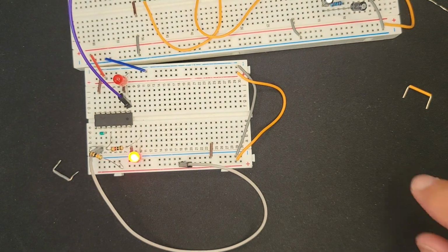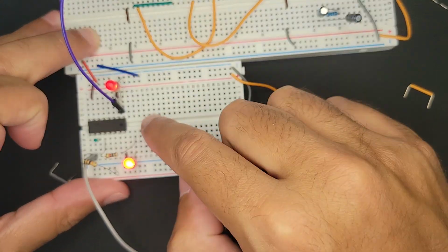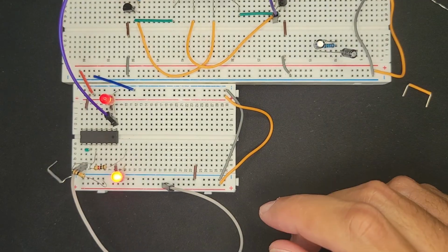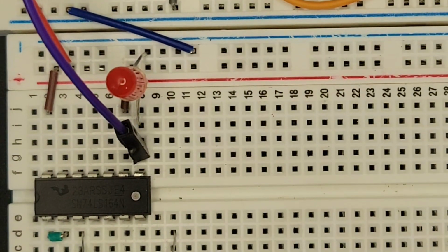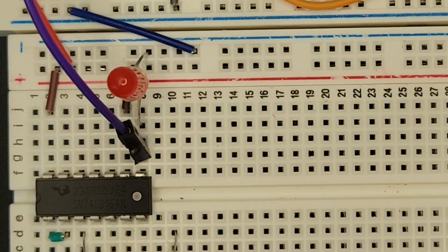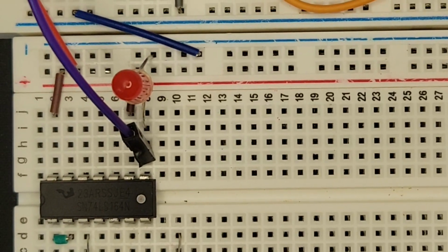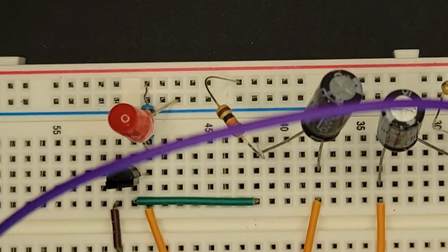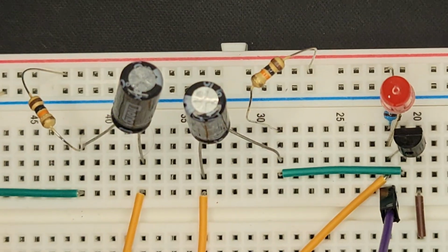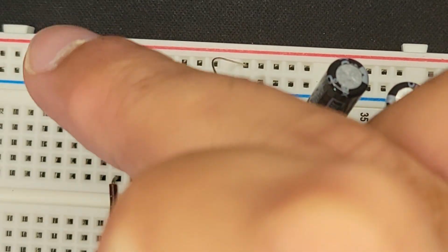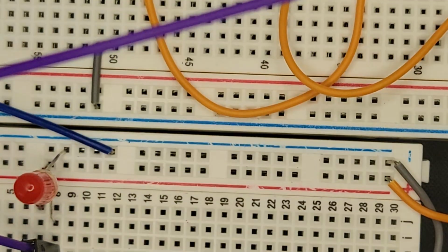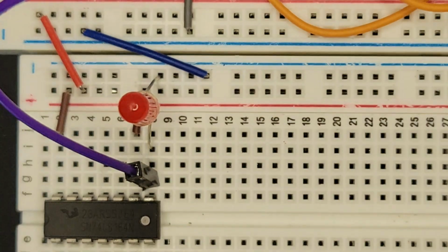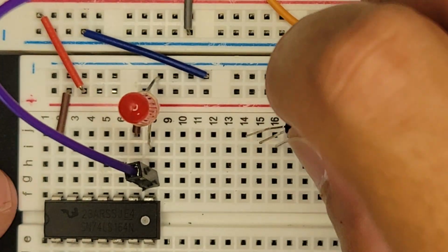I think I'm going to try and boost the voltage level with a transistor. So I'm going to plug up my power. I'm going to zoom in right here. And what we can do is just make a really simple inverter, because I don't really care whether it's in sync with the astable multivibrator or not. Although, you know, we really have 2 lights here. It's plugged out right now, but we have like a Q and a not Q, and I don't really care which one it lines up with. So an inverter is probably the best way I know to get a really high signal from a low signal.